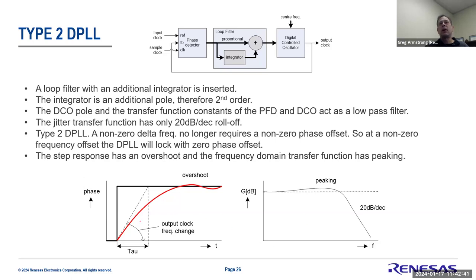And it's what a lot of times people talk about, like a gain peaking, which means if there happens to be a lot of noise very close to where we're trying to cut off or average out the error, if you don't have an integrator, if your integrator is too quick, you get a peaking. And that peaking can actually be very devastating in networks that you're trying to distribute a clock, because you're basically adding a noise component and it's basically a gaining of that noise throughout your network. So if you have like 20 nodes that are all introducing this gain, you're going to have a very bad clock traceability back to your fundamental source.